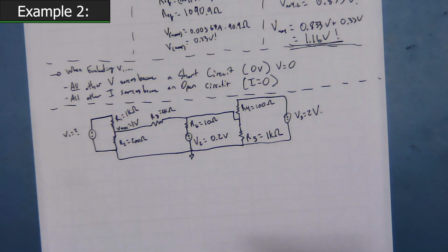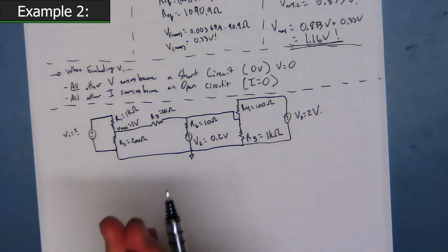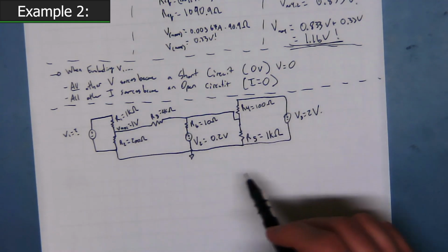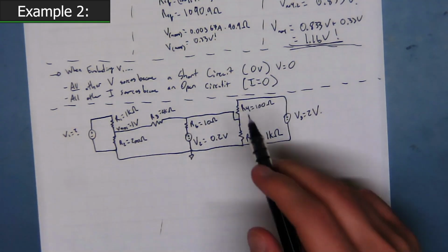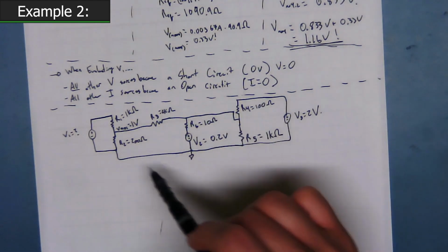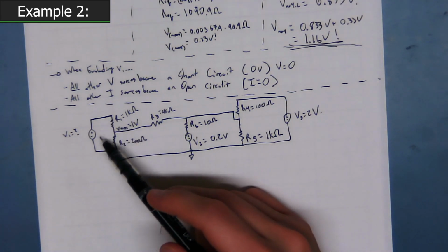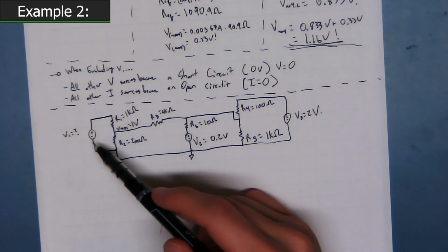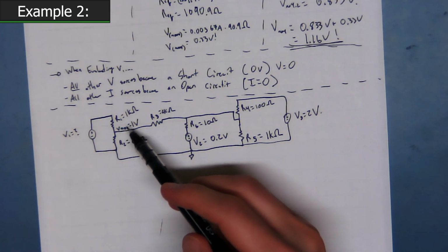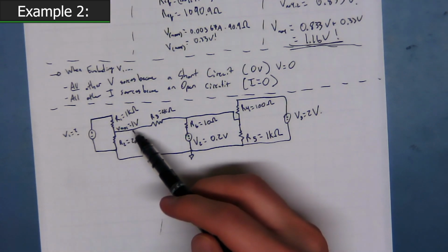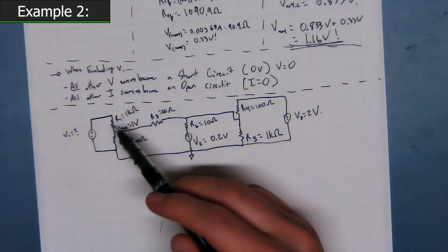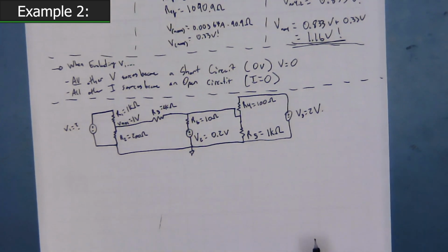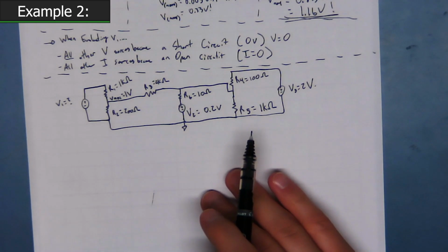Wow. That's a little crazier, but this is also very similar to some pretty real applications. Let's say you've got some kind of switch mode power supply controller or some kind of internal compensation something. Ooh, getting mad, I'm throwing things. Threw my pen. Anyways, so you've got some compensation network and some external feedback that you're dividing down a voltage source, say a critical something that you want to set a comparator threshold for, and you know that threshold's going to be 1 volt, or a switch mode power supply controller that has a feedback voltage of 1 volt nominally. Hey, this looks a little more applicable, okay? So yeah, it's more complicated, but it's also pretty cool. So let's try to break this down.